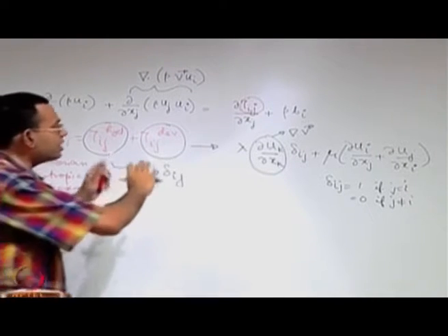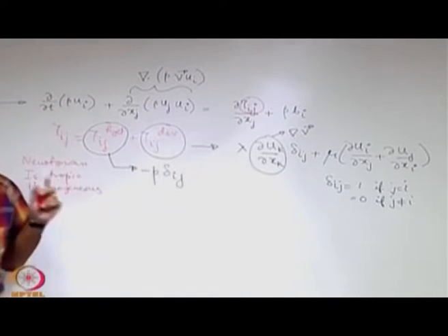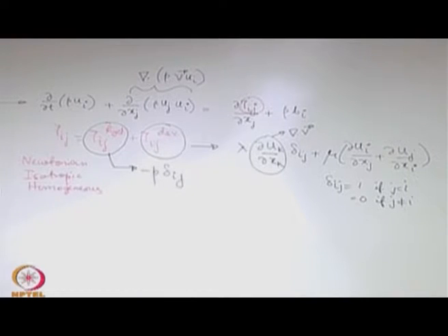We will try to see how these equations and unknowns may be closed, because one important understanding is that when you utilize this equation, you have to solve for velocity and pressure, these are the unknowns, and at the most you get 3 independent linear momentum conservation equations.